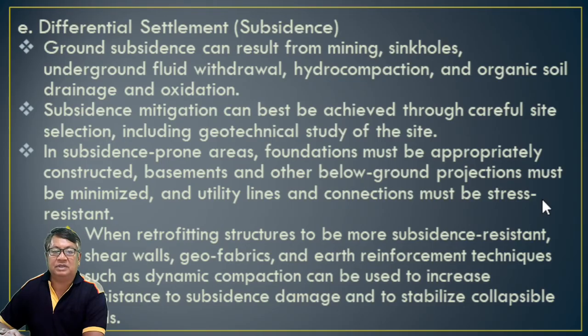connections must be stress-resistant. When retrofitting structures to be more subsidence-resistant, shear walls, geofabrics, and earth reinforcement techniques such as dynamic compaction can be used to increase resistance to subsidence damage and to stabilize collapsible soils.